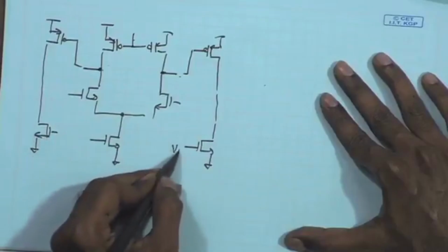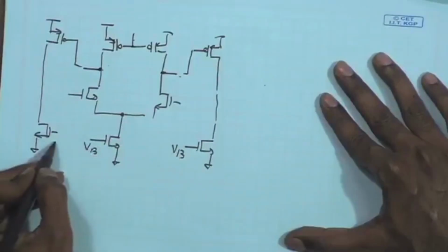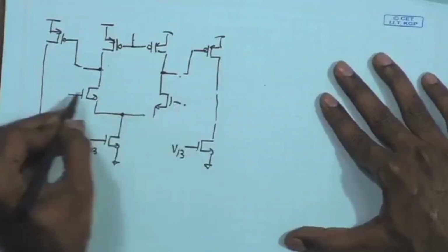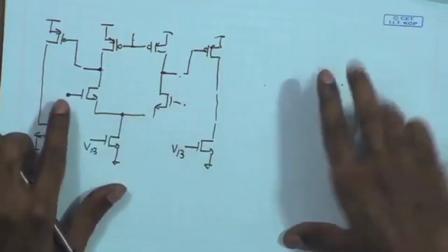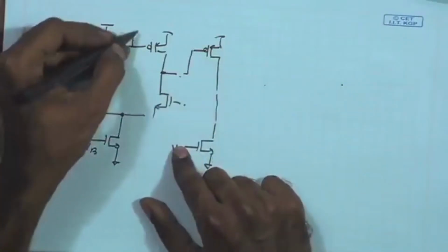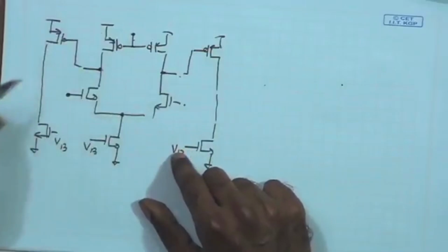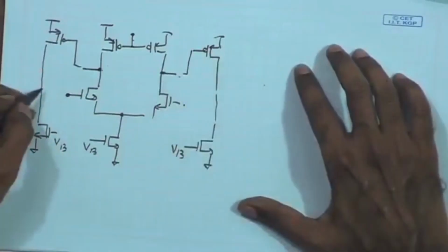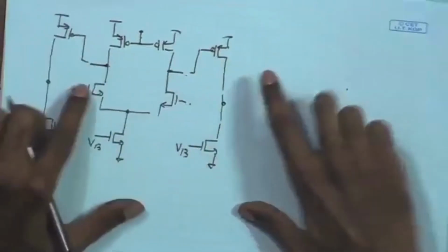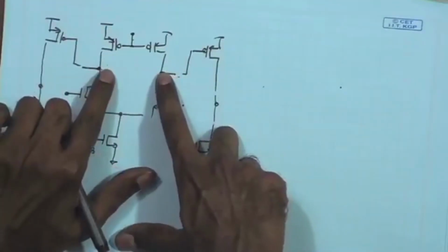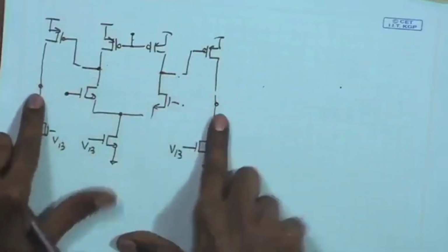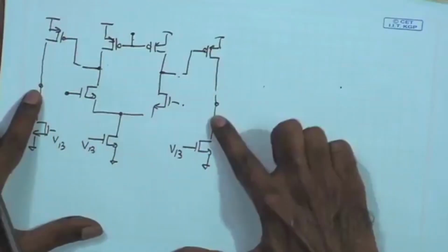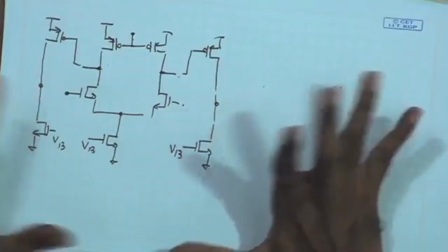So, this is VB, which is a fixed bias point, and your inputs are over here. I am not showing the input bias point for the main amplifier. Here in this case we have the first output, which is active load, which is not having a well defined DC point, and the second output is also an active load, which is also not having a well defined DC point. What is the overall gain of this circuit?